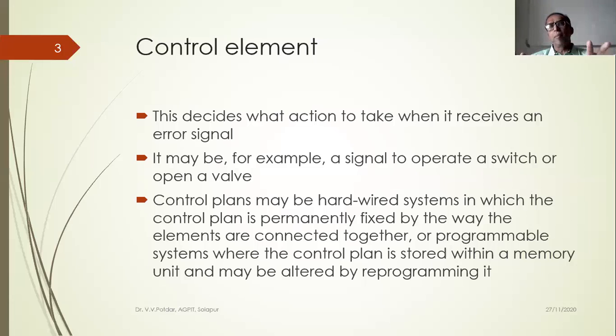Once the programmable logic controller or programmable controller receives the error signal, it scans through the error signal, and in the set program, it will compare, corresponding to this error value, what is the expected control action, and accordingly it will generate the control signal. So it can be either unprogrammed or a programmable system where the control plan is stored within a memory unit and may be altered by reprogramming it. So this control element is a very important element in this control system layout.